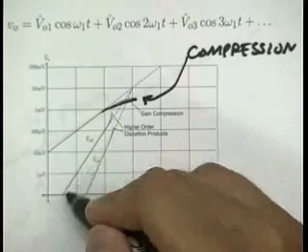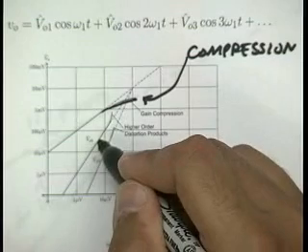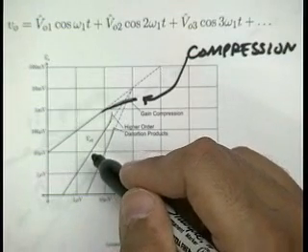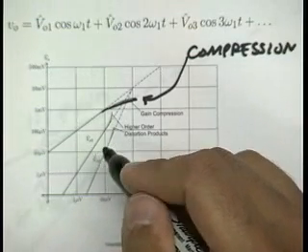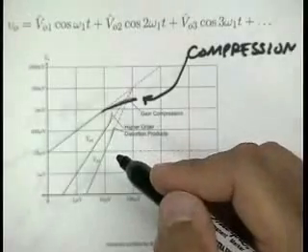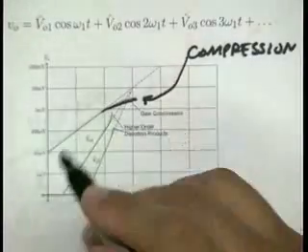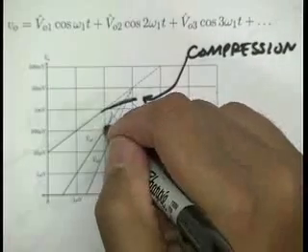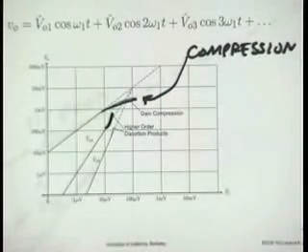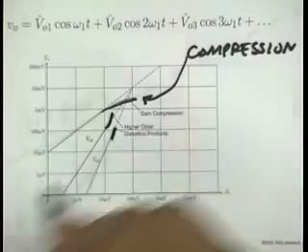You can see the second order follows this 2 to 1 curve. That's when the second power is dominating the second harmonic. But when the fourth order term comes in, the slope should change to 4 to 1. The sixth order comes in, the slope should change to 6 to 1. So we see the slope going way up here. Likewise for the cubic term.